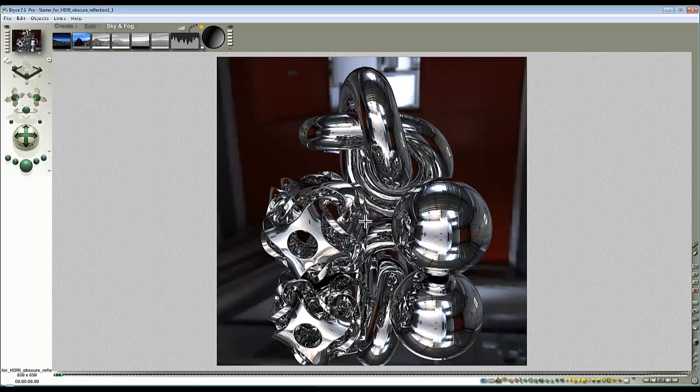But there's a bit more to it than that, and the main problem in understanding the role of this backdrop and how it works with reflection is that the monitor that you're viewing this through is only low dynamic range. Once you get up to fully white, RGB 255, 255, 255, you've essentially hit the limit of what can be displayed. So these areas here are actually a lot brighter in terms of the rendering calculations. The values being operated upon are much brighter, but when they come to the monitor they have to be brought into range where they can be displayed. So even if these are fantastically bright, they can only look fully white.